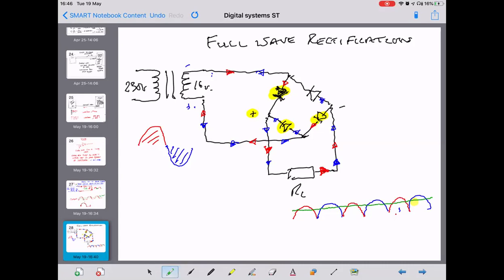So what you can do with this bridge is you can either build a bridge out of separate diodes, or you buy a package that's got 4 diodes already built in it, just 4 terminals coming out of the package, 2 marked AC and 1 marked plus and minus DC. And that's just a 4 diode bridge rectifier. Okay, a number of different ones, from tiny currents up to several tens of amps. All right, so there's a widespread use of diodes in power supplies.